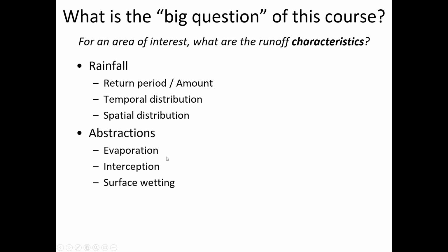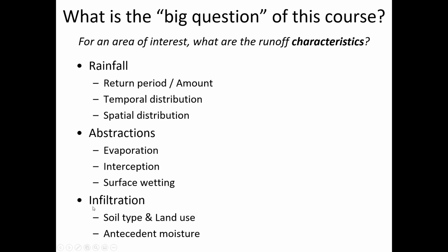So all of these different factors, we've talked about some kind of either an underlying fundamental principle that tells us relatively more, relatively less runoff, depending on slope, depending on the density of the drainage within the watershed. We've talked about a lot of these factors to try and estimate their effects. Now, infiltration, of course, the two methods we talked about were Green-Ampt and then the Horton method. And these are ways to estimate the declining potential rate of infiltration and how the suction head decreases as the pores begin to fill during an infiltration event.